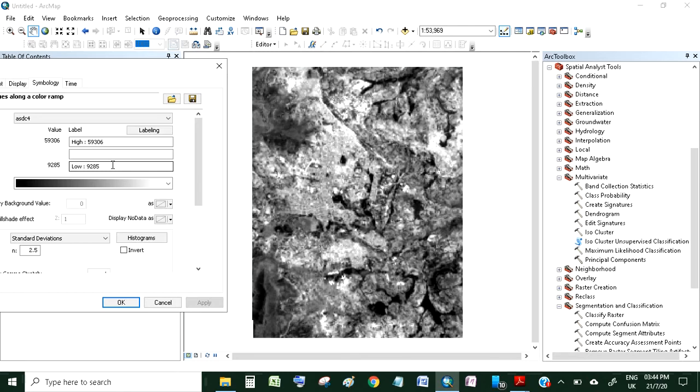So most of the variance within the study area can be explained by the elevation. So elevation data is important because it is giving us much more information. The result of the tool is a multi-band raster in PCA with the same number of bands as specified in the number of components.